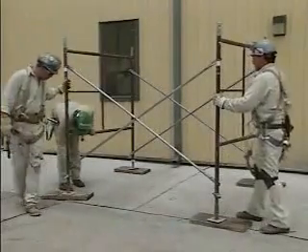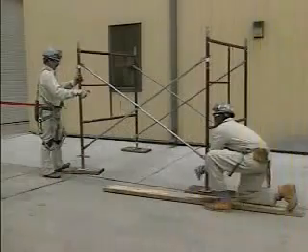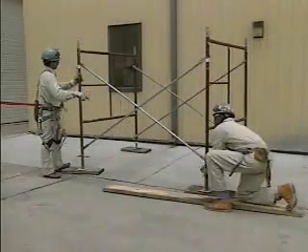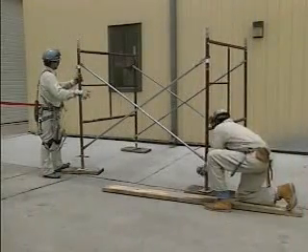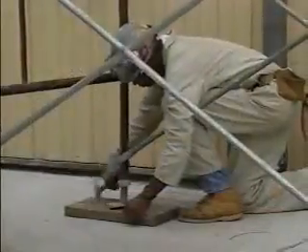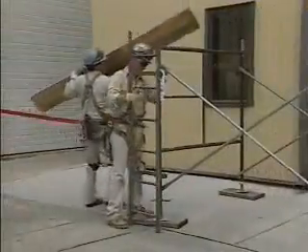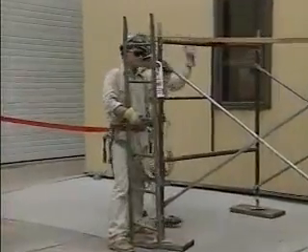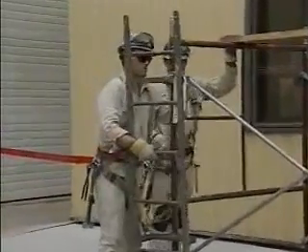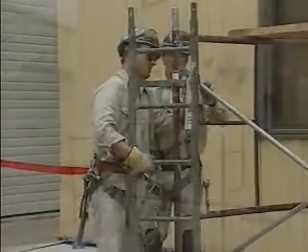Cross braces are then connected between the two end frames to strengthen the scaffold. At this point, a bubble level is used to level and plumb the framework to ensure that the scaffold will be stable. And the base plates are nailed to the sills. The first section of the scaffold ladder is then put in place, and a scaffold plank is laid across the tops of the end frames so that the builders can assemble the next level.